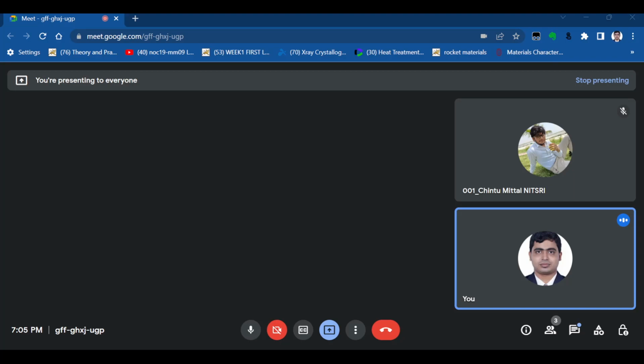So remember, if you have to calculate the fraction of liquid, so this one is our liquidus line, right? So you have to take this BD, this whole length, okay, fraction of liquid for 47 weight percent nickel.